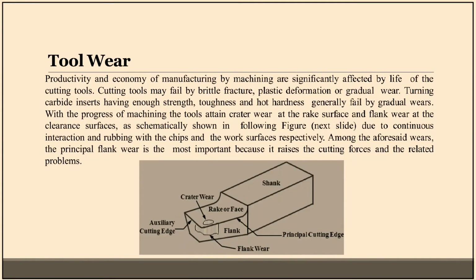Tool wear. Productivity and economy of manufacturing by machining are significantly affected by the life of the cutting tools. Cutting tools may fail by brittle fracture, plastic deformation, or gradual wear. Turning carbide inserts having enough strength, toughness, and hot hardness generally fail by gradual wear.